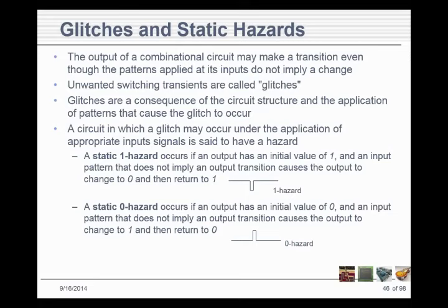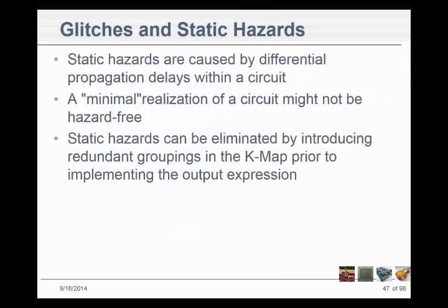And we'd set it to stop on a glitch, and it would stop, and it would put a bunch of stuff in the buffer. It's always storing stuff in the buffer, but it would have it beforehand, see the glitch, and then it would keep what it had beforehand and save a bunch more after that, and then display that on the screen for you to work with back and forth and try to figure out what was going on. Great machines, but we don't have them anymore.